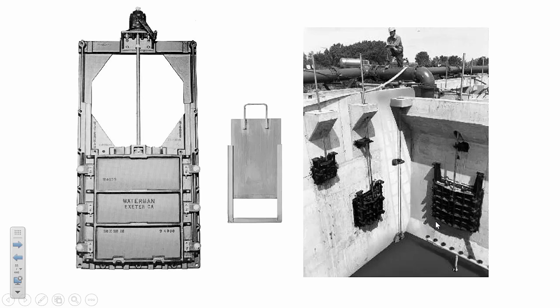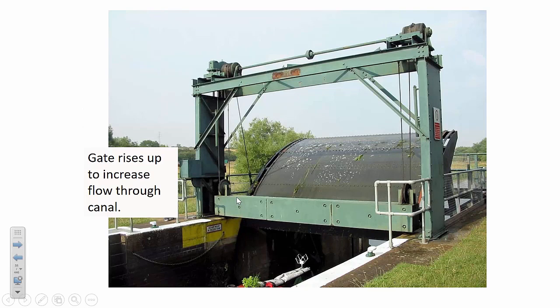Gates like this are used both in irrigation applications, but also they're used a lot in water and wastewater treatment, just to regulate flow in and out of stilling basins, aeration basins, flow equalization basins, disinfection tanks, and so on. So it's pretty important to be able to predict the flow performance through a gate.